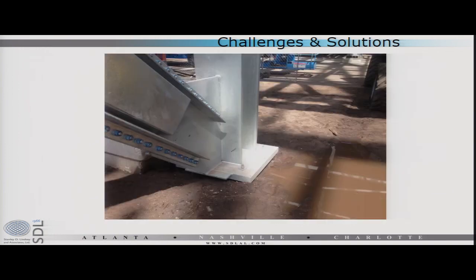Well, one of the ways is stop doing things like this, right? This is on one of my jobs. This is a 14 by 300 and something with an HSS 14 brace, and it has 4 3/4-inch anchor rods. Stop that. You know who you are. Do something reasonable, right? This worked in the final condition because the building was so heavy that friction worked. Works great in the final condition. It does not work great when you're setting the column and when you don't have all of that load on it. It's not very costly to upsize an anchor rod in the design phase.